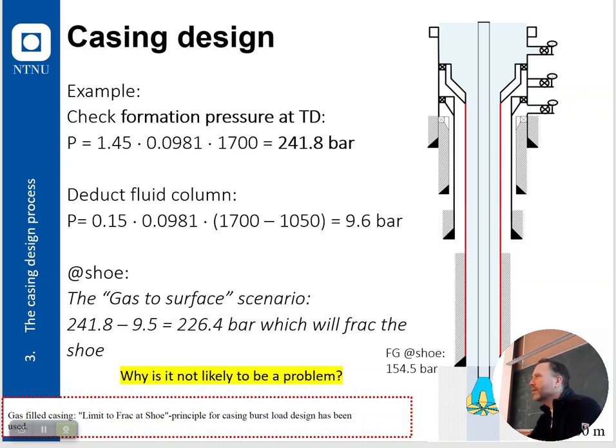You say that you use brine in other countries. What do you use? In other countries where I've been drilling, we used brine to kill the well. We have to use stuff with pore plugging material, for example, mud. So you bullhead, and typically in these wells that are producing hydrocarbons, you would use a cushion of base oil.